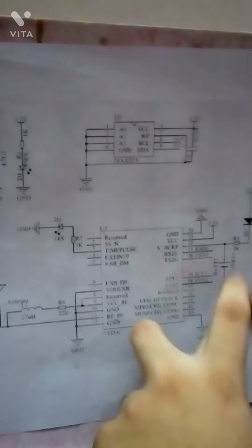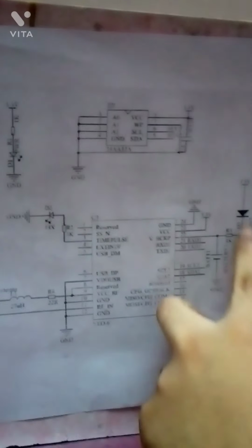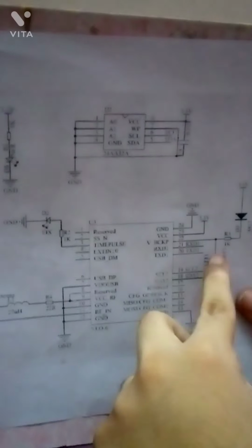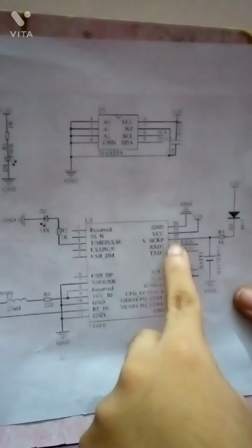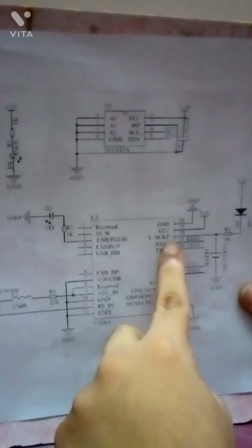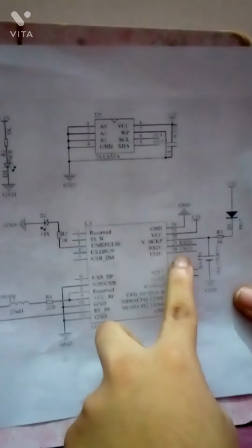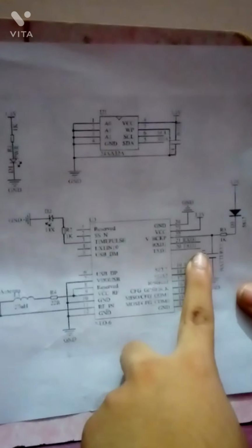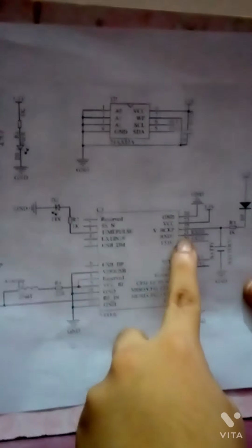So that's why this battery is not overcharged. I mean, this battery is not over voltage. There is a 1 kilo ohm resistor and diode for priority from 3.3 volt, and ground to battery ground. And the battery positive is also connected to pin number 2 of this IC, which is the backup volt battery pin. And pin number 20 or 21 is connected to the output: 21 is receive and 20 is transmit.